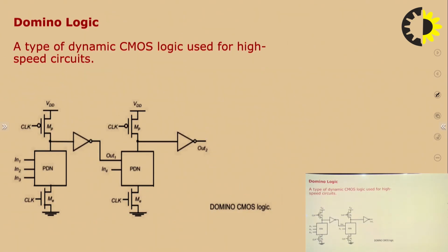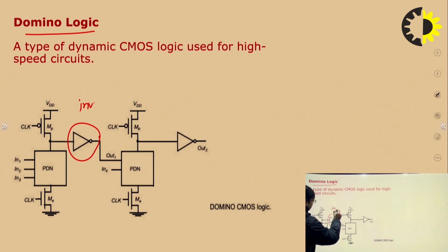Now, a possible solution for this problem is to use domino logic. What we do in domino logic is we insert an inverter at the output of each stage.